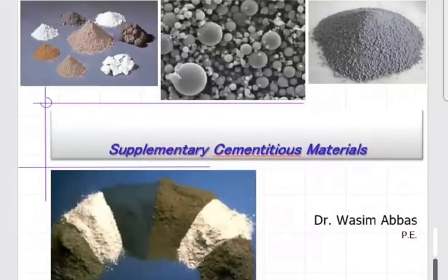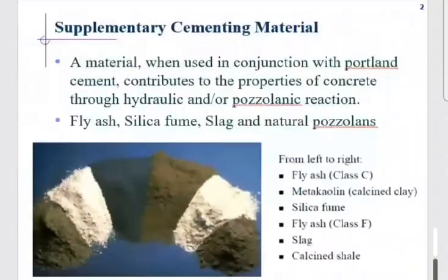Cementitious materials. These materials are called the materials which can supplement the cementitious properties. These are the byproducts which are used in conjunction with the cement and which contribute towards the binding ability of the cement through pozzolanic reaction.